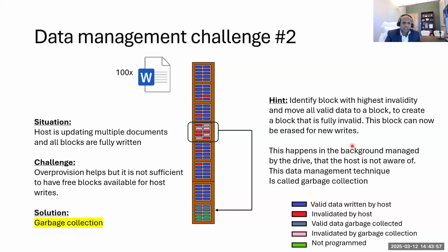Does that require specialized peripheral circuitry to handle this? No, standard peripheral. It's all managed by the firmware internally. Okay. Yeah. So the writes happen the same way as host writes. If the host is writing data, the way data is written to new locations on NAND media is the same way, but we just have to write firmware in such a way that we identify blocks and then read the data and move them to a different location. So no additional hardware is required for this purpose.